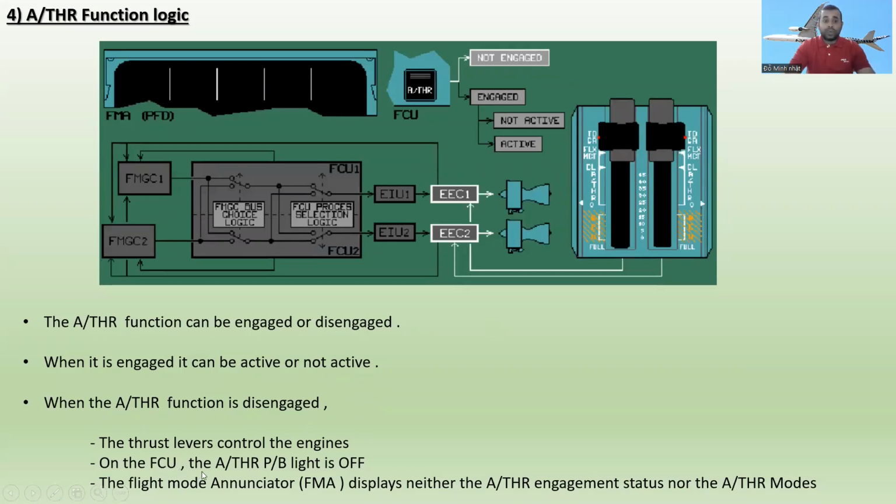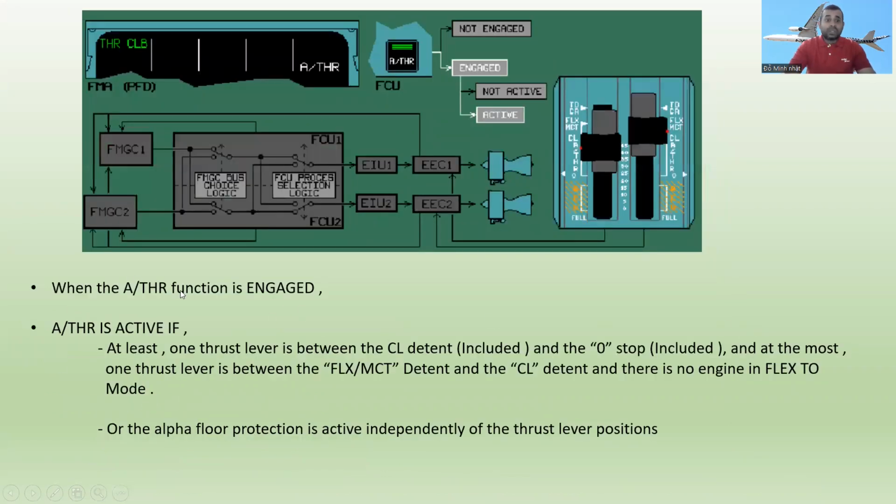On the flight control unit, the autothrust push button light goes off, and the flight mode annunciator displays neither the autothrust engagement status nor the autothrust modes. Just remember it. And when the autothrust function is engaged...